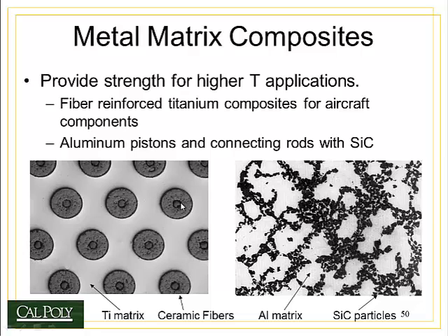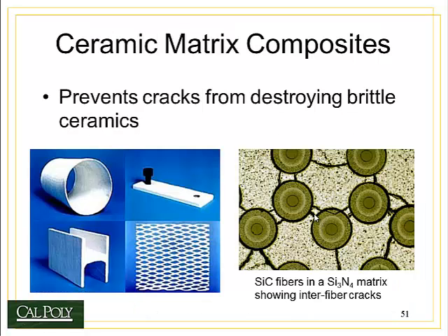One of the problems with both of these composites is anisotropy. The properties in the direction of the fibers here are going to be very different than the properties out of plane of the fiber. Likewise, you can see that the chunks clump together or agglomerate. That means that the modulus of the material where it's just pure white, or the pure aluminum, is going to be much different than the elastic modulus over here, where I have lots of chunks of ceramic reinforcement.